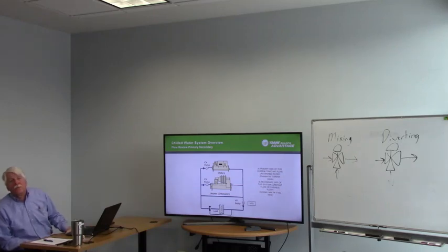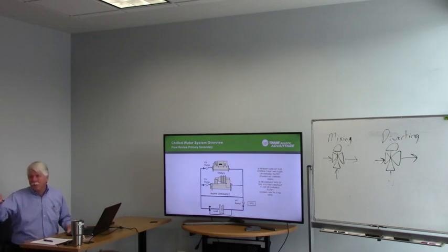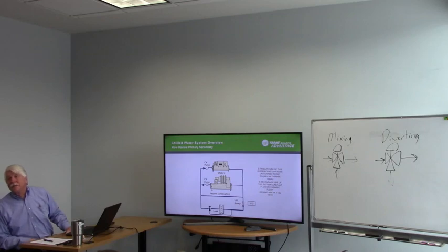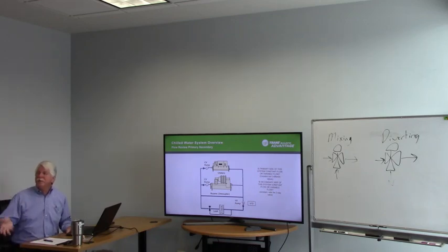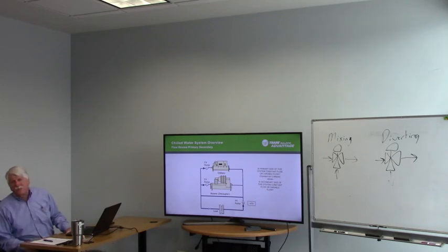By the way, does anybody know why you use VFDs on constant flow systems? Balancing, that's a very good one. Yes, you can use it for balancing. And motor starters are really loud when they get old. Soft starts, yeah. A VFD will bring a motor up to speed more slowly. It's not as much of a shock to the system. Okay, now, I took the three-way valve out. Now, is the secondary side of this constant flow or variable flow? Now it's variable flow, that's right.